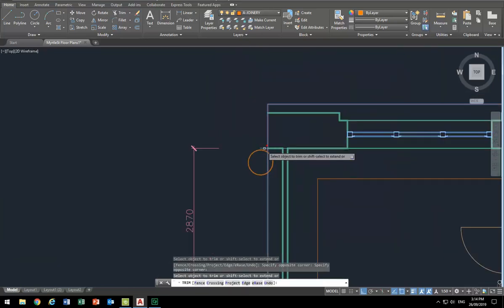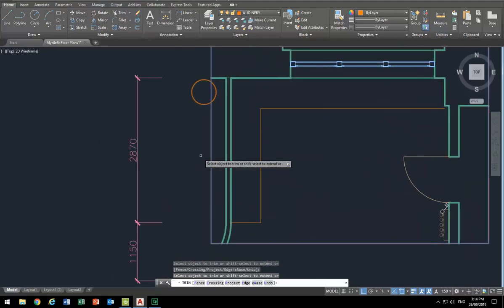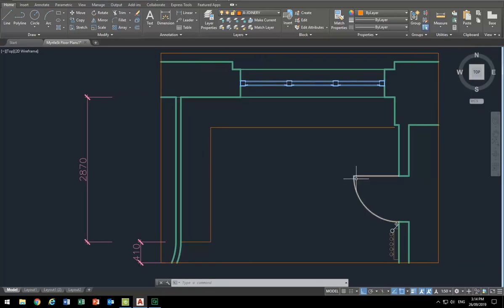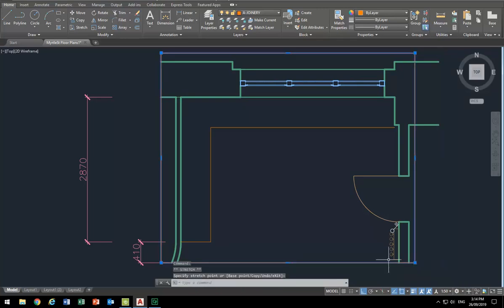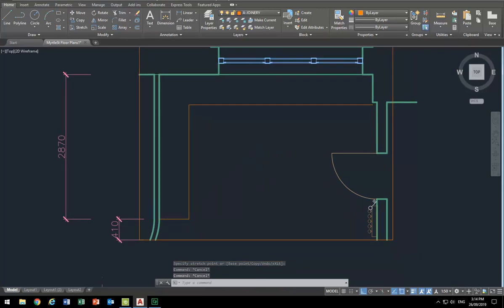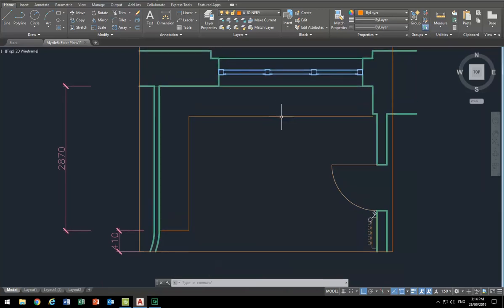Now, you can do joinery drawings without the surrounding walls, but if you need to locate the units against the wall, it doesn't hurt to have the walls there, but make sure that they're hatched or you've got some indication that they're not part of the joinery set. In other words, the cabinet makers won't think that they need to build anything that's not necessary, and that's a common problem when they're not sure what's part of the drawings that they should be using.